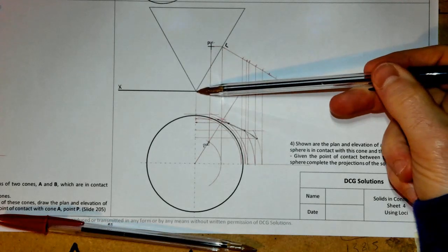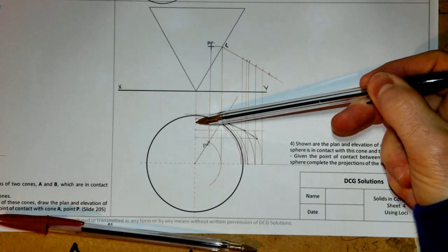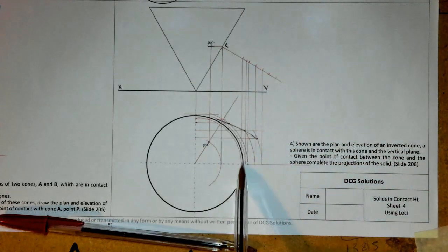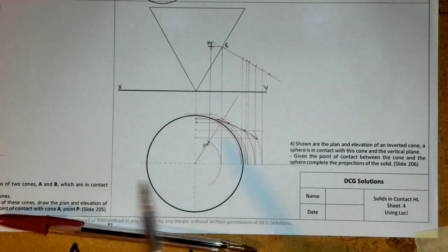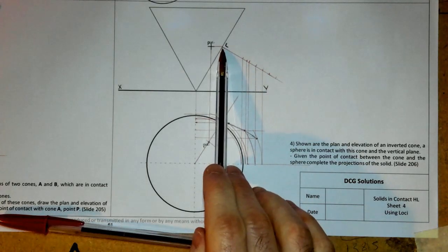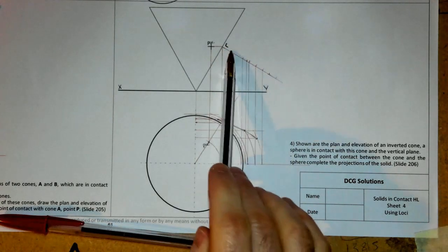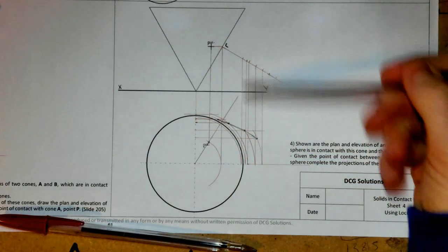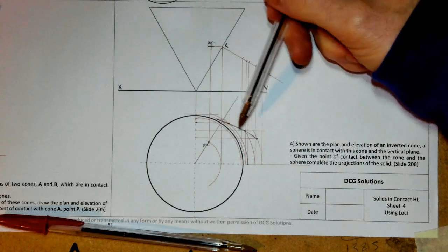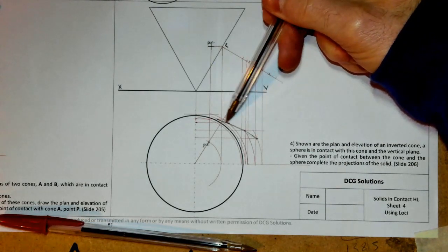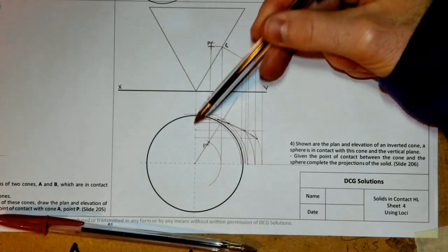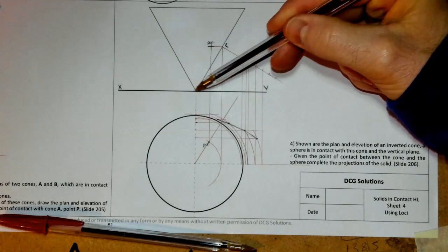So I've marked down here 18, 20, 25, 30, and then from them, when I brought them down, I had to project them up, okay? So that's the confusing part, is when you bring them out along what would be where the center is joining up to the point of contact. You have to project them down and then rotate them up. So that's a little bit tricky there. But anyway, what I've got here, you can see here, I've sketched it in. I've got the locus of a point, or the path of a point, that's equidistant from where the point of contact is and the vertical plane.